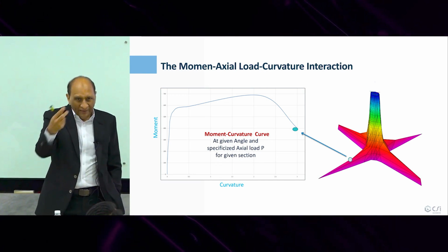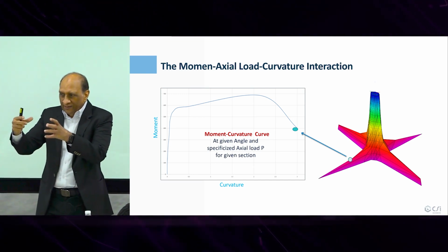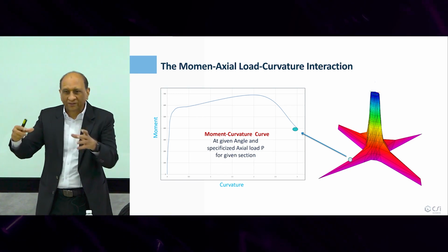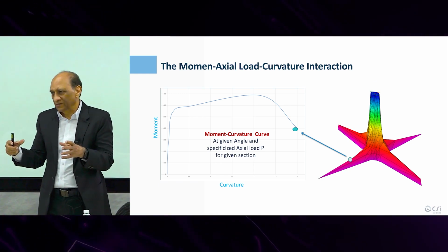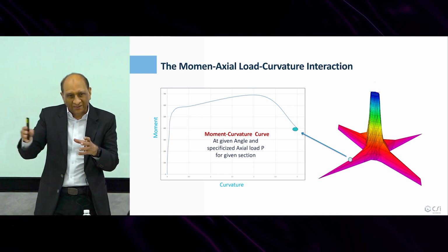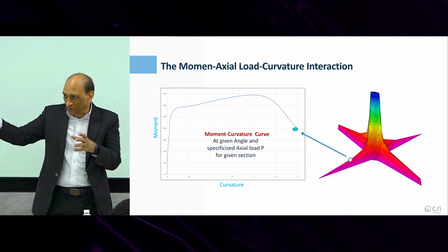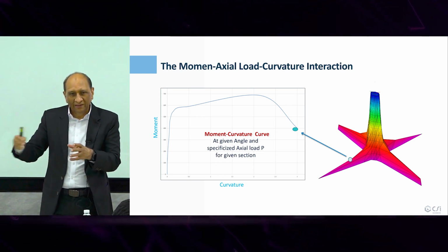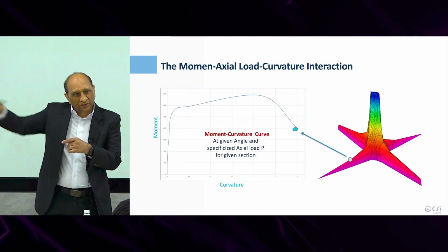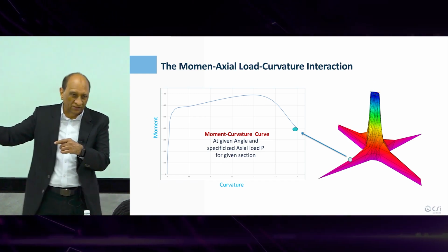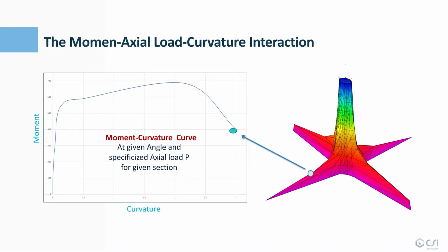But as you go up, as the axial load is increased, it doesn't matter so much because now the compression is uniformly distributed. It's not going to make any difference because neutral axis starts at a depth, not at the corner. But for zero moment, neutral axis depth is very small, and then only the corner is under compression, which is gone. So that's why you get this plot.